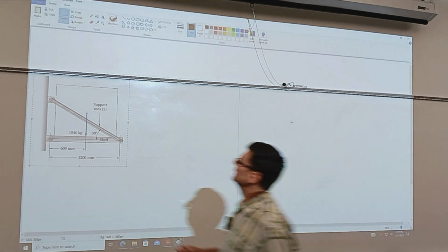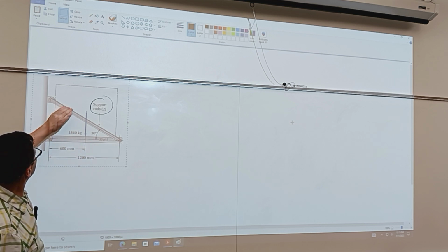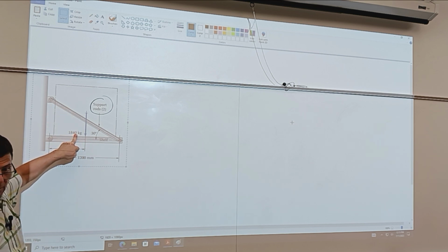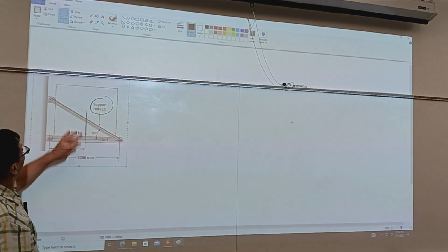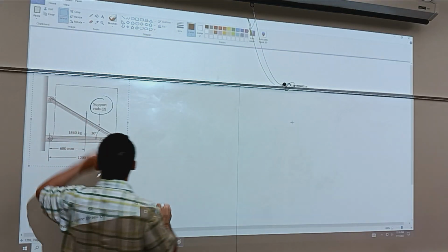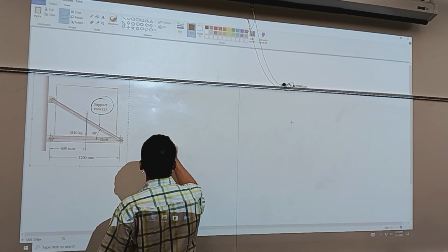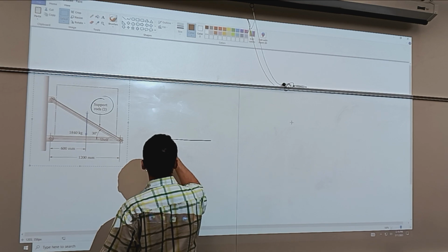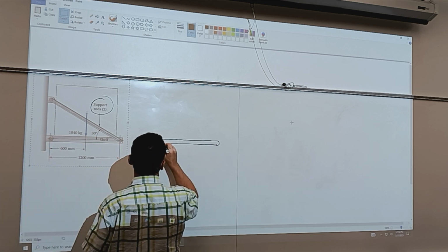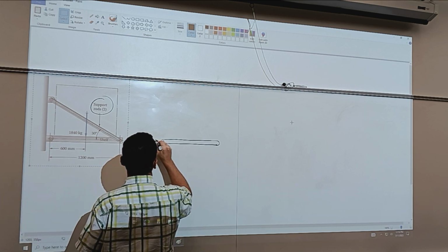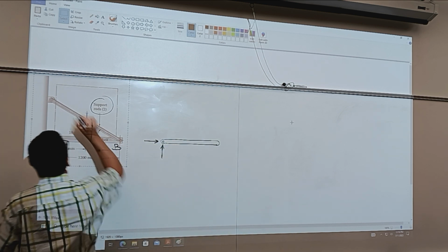So again, there are two rods. In the model that includes just one rod, we're going to take half of the load, for that reason. And we need to do a free body diagram, which is helpful to calculate the tension in the rod. We can do a free body diagram for each individual member. So we have the lower, the shelf that is, and here we have a pin joint, so there will be reactions, and we're assuming them to be positive. So let's call this A, B, and C.